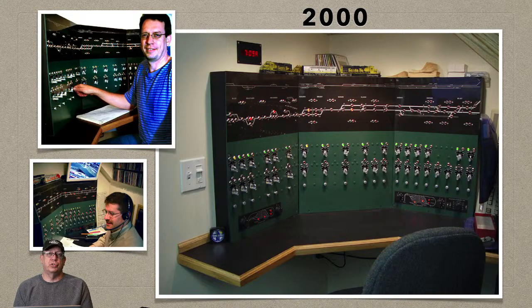Signaling really serves two purposes. The first thing is it's to provide authority, which means, hey, your signal's green, you can move now. And then it provides protection, which means once you move, the signals behind you and the signals in front of you turn red to keep other trains from coming and hitting you. So authority and protection are the two big things that we talk about when we talk about signaling.